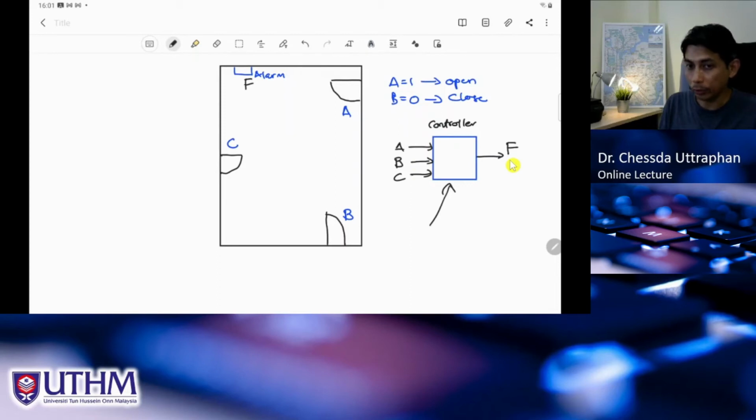So we can use data flow modeling, where we need to derive the Boolean equation first and then design the circuit. Or we can also design using structural modeling, because again we can derive the schematic for this. Again, it is because the circuit is relatively small, 3 inputs 1 output, we can derive the Boolean equation.